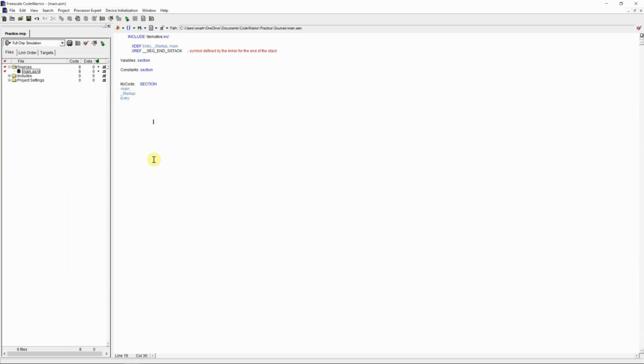The next addressing mode is called direct addressing mode. Now, if you understand direct addressing mode, it'll be very easy to then pick up the remaining addressing modes. So far, every time we wanted to access data or store data in accumulators, we would use the pound sign to grab the number after it and store that into the accumulator, and we said that that is called immediate addressing mode. But most of the time, you would need to actually address or access memory and grab the content in memory and store that into the accumulator.